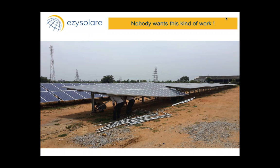Gurpreet, what is your opinion? What do you see in this structure? Do you see what has gone wrong here? Essentially, the design part of it. Seasonal tilt has recently gained a lot of attention, though it was not used earlier. But the incremental cost of converting a fixed tilt into seasonal is not much. So, this is one of the preferred structural solutions today.